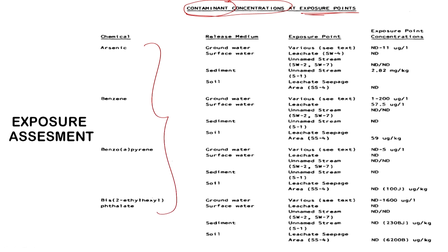Let us say I am the human living in the vicinity, I am the receptor. I am concerned about what the concentration is at my particular point of usage, not what the concentration is at the landfill. So, obviously again for the chosen compounds, arsenic, benzene and so on, we look at the exposure point concentration. If you go back to the relevant slides earlier, you see that the concentrations are either low or not detected.